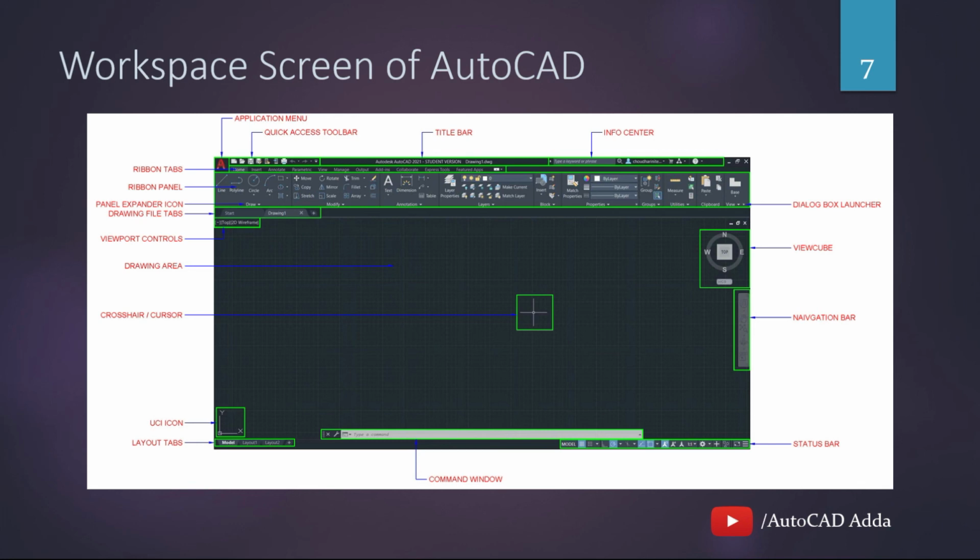You can create your drawing sheets of different sizes and scales as per the requirement. You can add a title block, name of the project, date of the drawing, etc. and select the components to be shown from model space. It is to be noted that the model space tab cannot be deleted and there cannot be more than one.